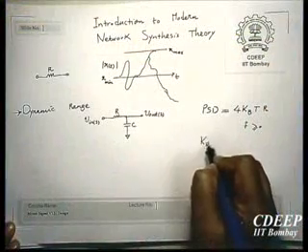We don't have any ideal white noise practically, however we can approximate it at least in the range of frequencies we deal with. So, at least in the context of this course, thermal noise of a resistor will be white. Here k is the Boltzmann constant.